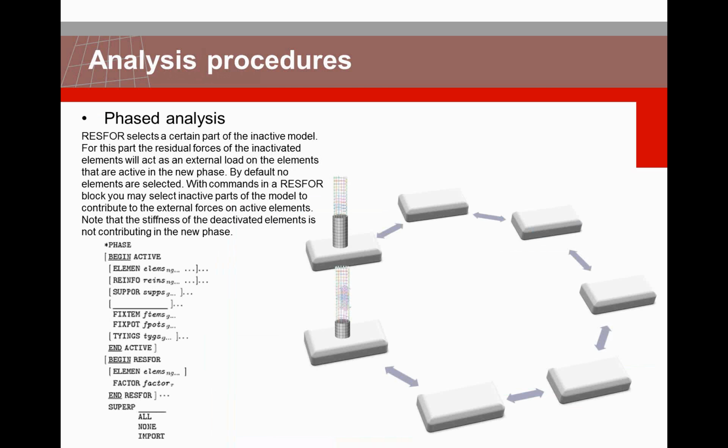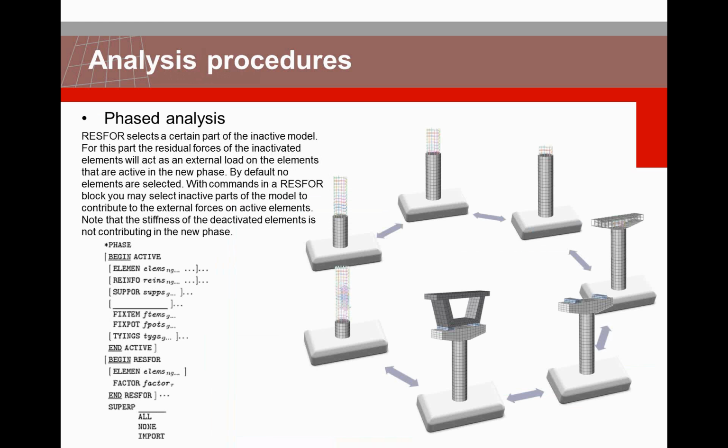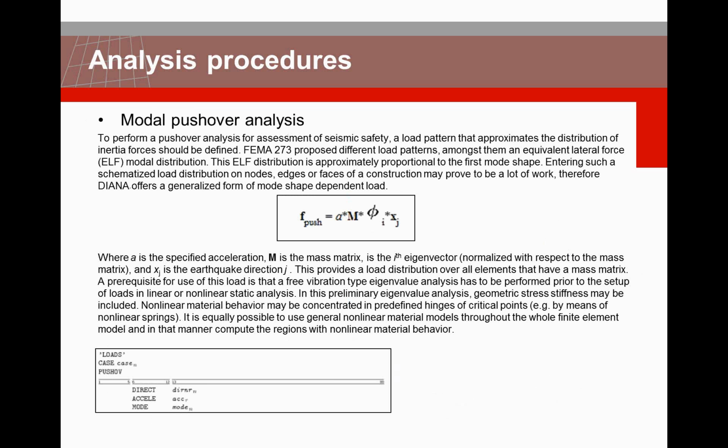What we see in this sheet is another extension of phased construction analysis, and that's the functionality in which in an excavation analysis the internal forces of the elements that are removed can be maintained in following phases. And this is very common functionality used in tunnel excavation analysis.